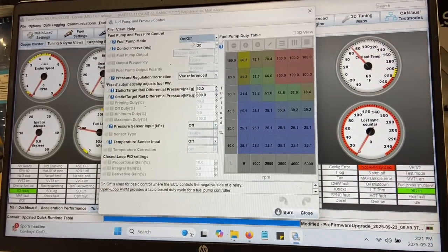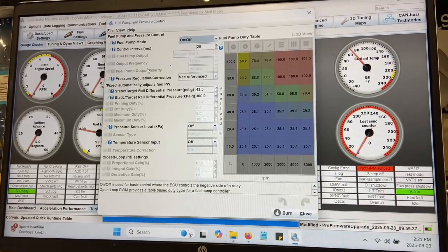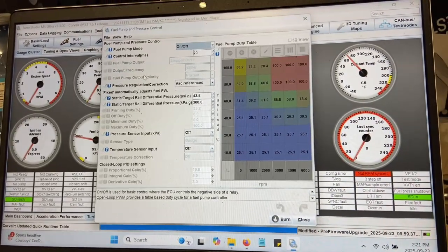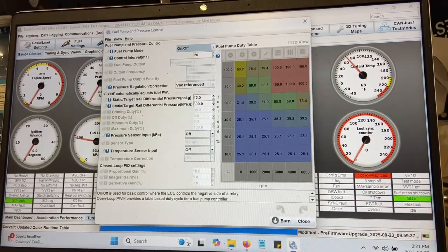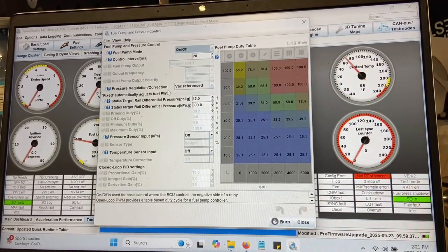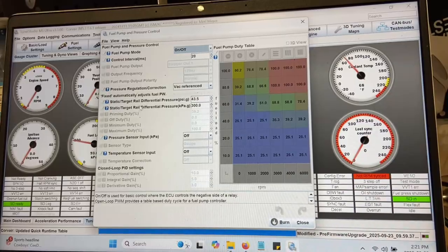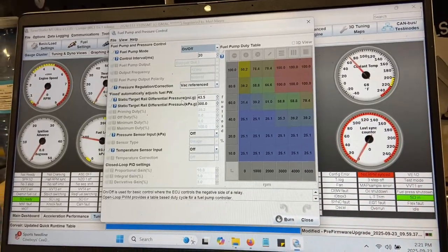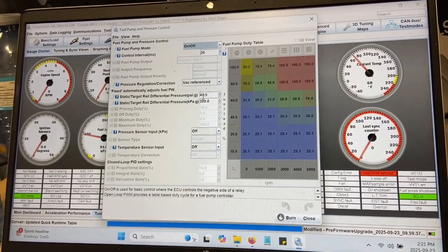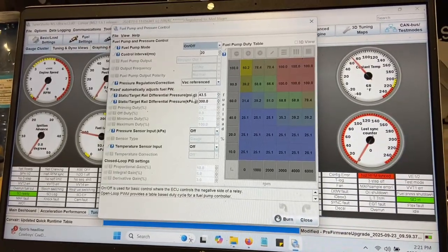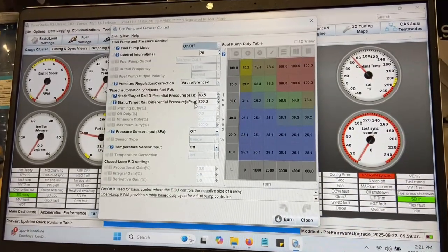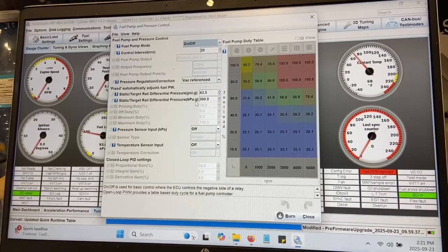So my relay is turned on and off wherever the ECU wants it on and off. So when I turn the key on, it charges the system, and so on. Then I'm using a vacuum referenced regulator. We'll look at that. And my static pressure, I want to have at 43.5 PSI, which if you convert that into kPa, is 299.92 something, so 300 kPa.